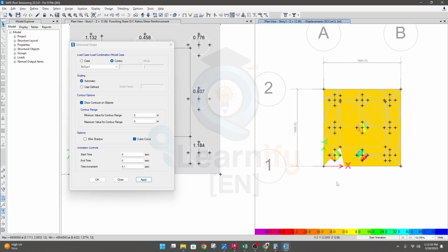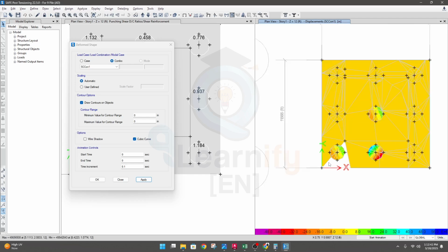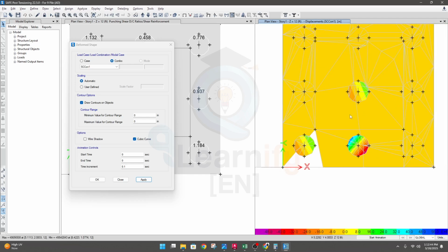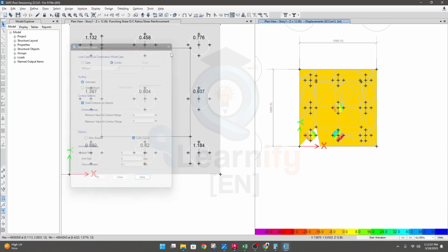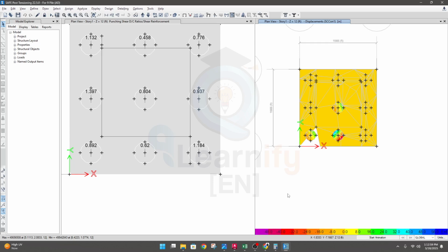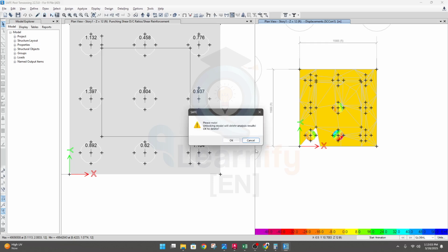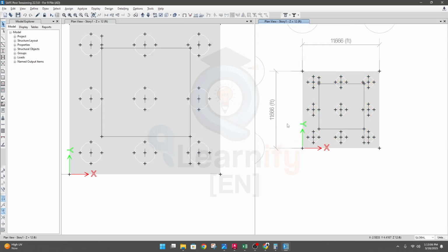Okay, so now what we'll do, actually our main mat is not displacing, but because of that irregular meshing, you can see here, because of irregular meshing, here we are getting this issue actually. So I'll close it, check again, and go for this solution.